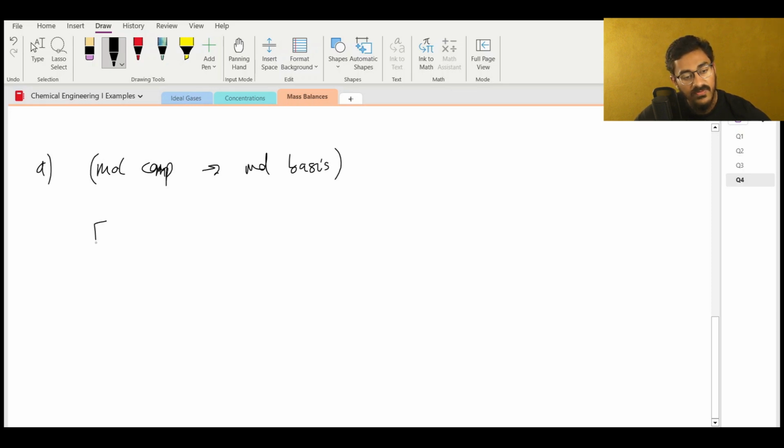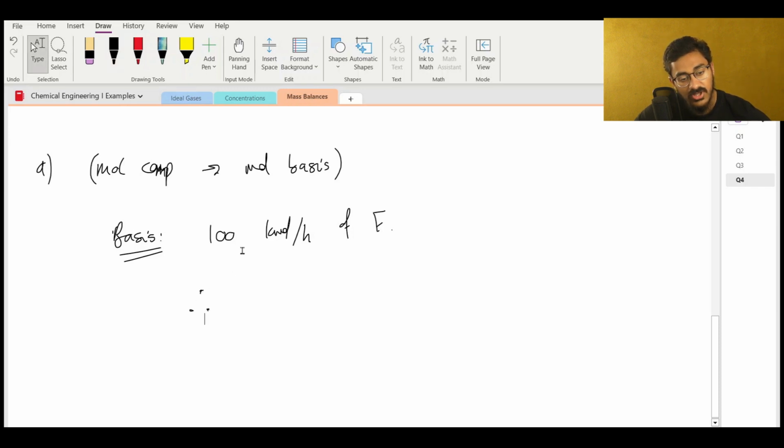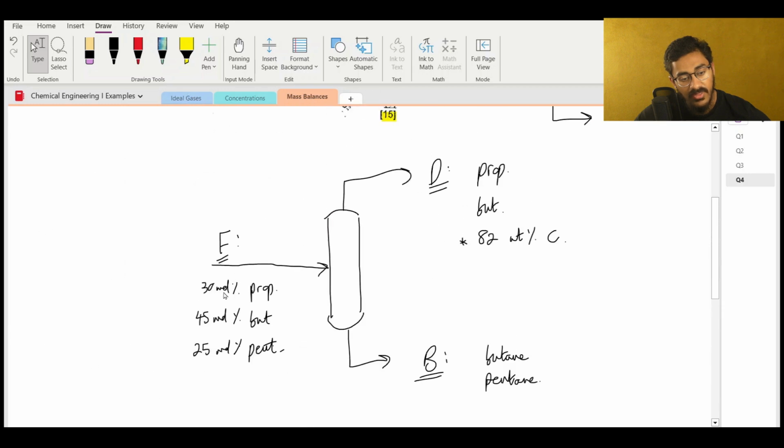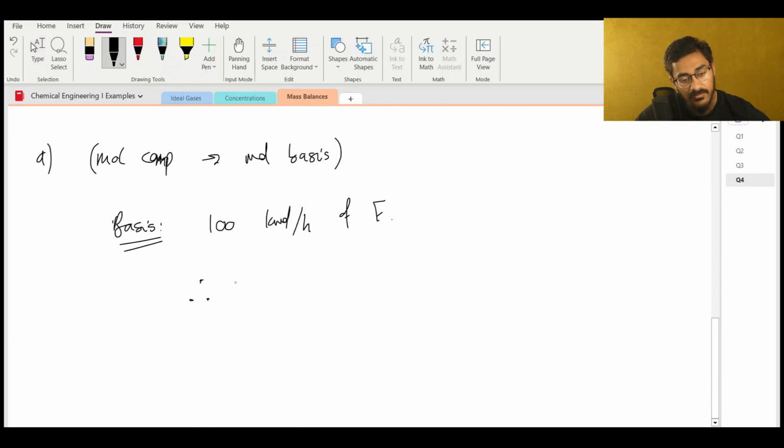So in my feed stream, or actually over the whole system, sorry, I'm going to say that my basis is 100 kilomoles per hour of the feed stream. And therefore, if I've got 100 kilomoles per hour coming in, then I know I've got 30 kilomoles per hour of propane. So let's write that down.